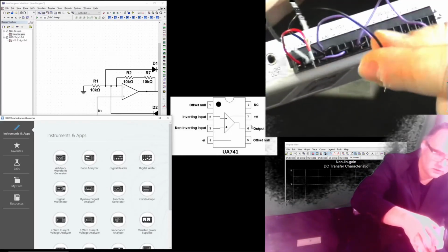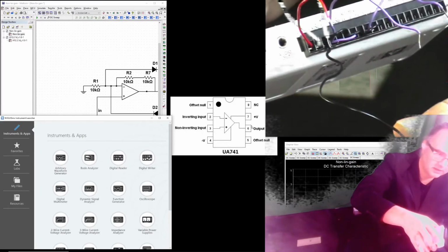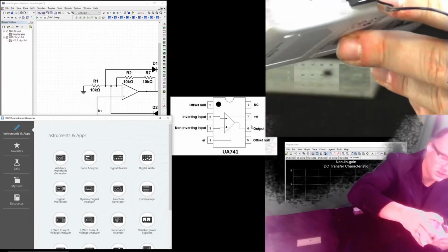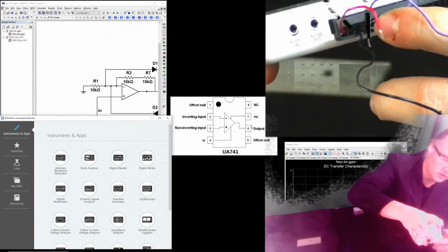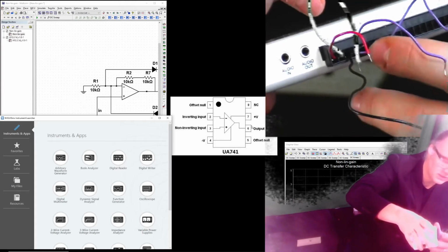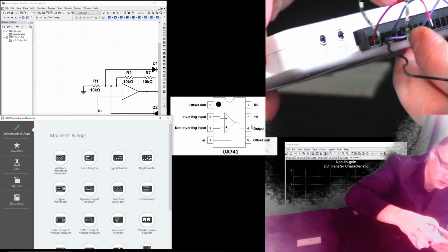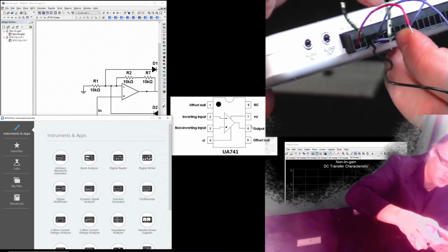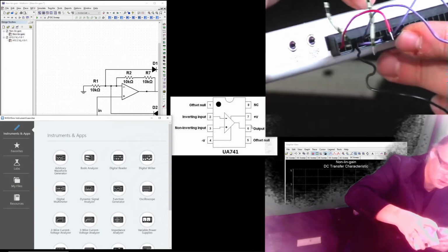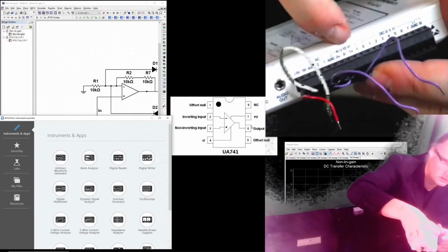And this goes one cable, the black one, will be the analog ground, which is connected to the analog ground here locally of the input, which is connected locally to the analog input minus 0, and locally to the analog input 1, the negative input.